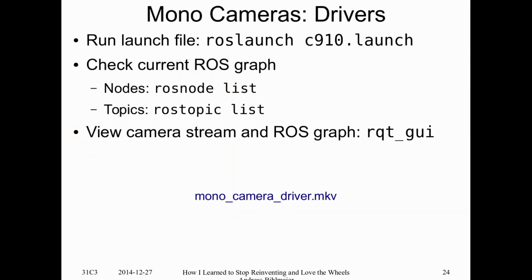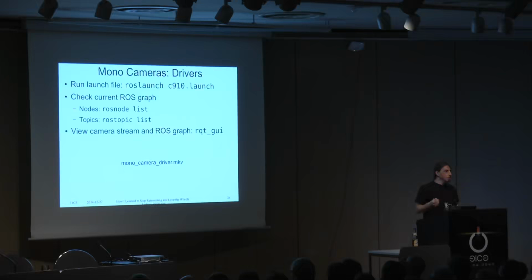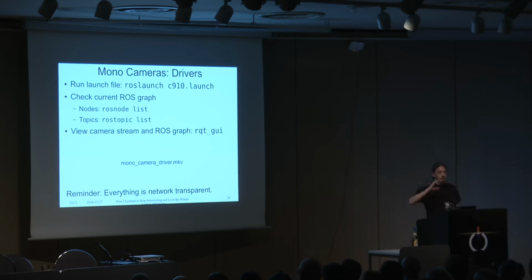during runtime. So I did not have to recompile my camera driver node, adding debug output, for example, OpenCV image show. I can just, at runtime, start my GUI, and it will connect as a subscriber to my data stream and also get a copy of the information. All other nodes keep on running. And this would have been working exactly the same way whether I started the camera locally and the RQT GUI locally, or one of those remote and the ROS core on a third computer.